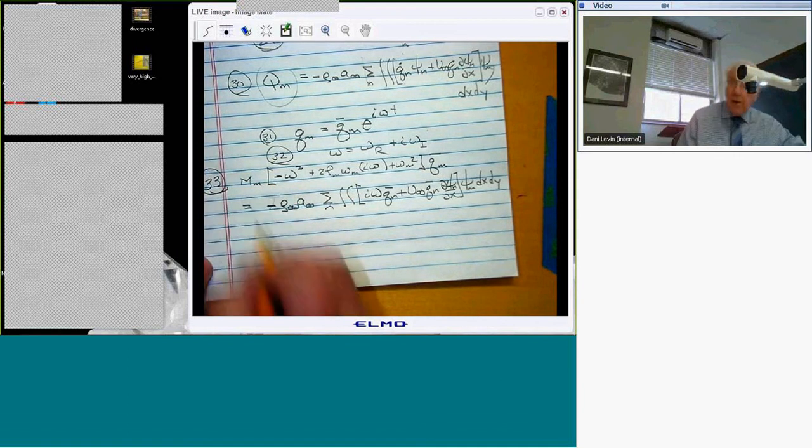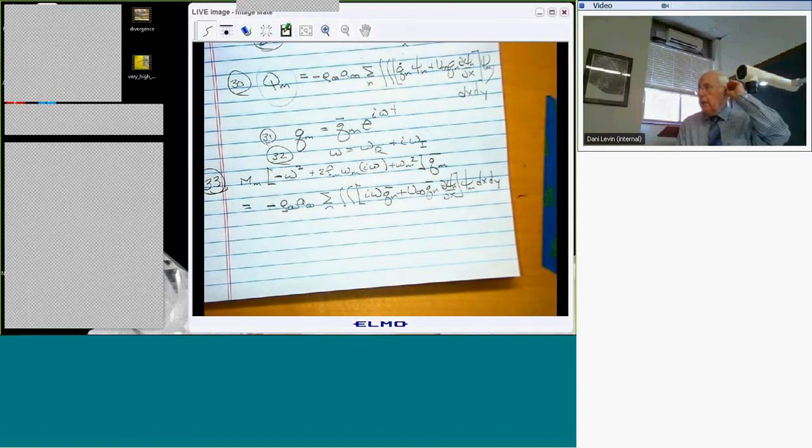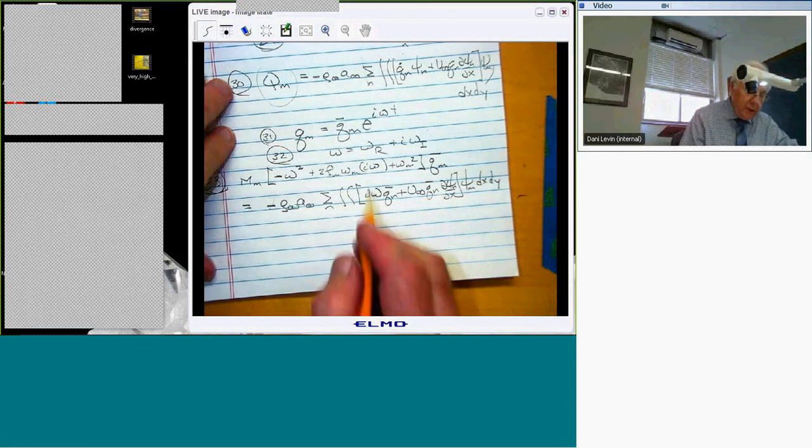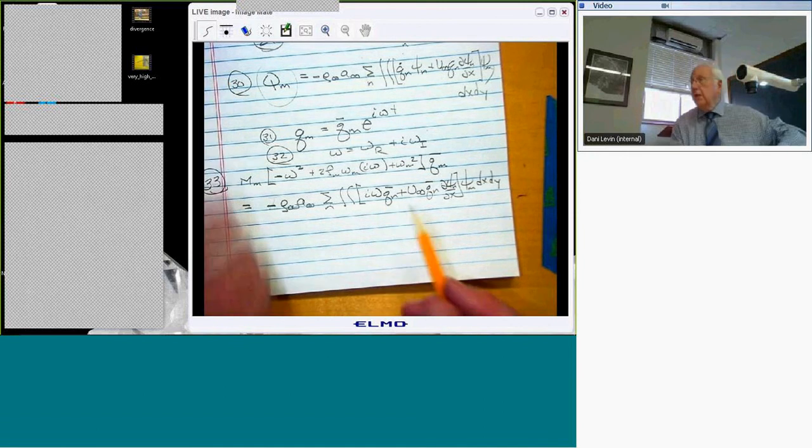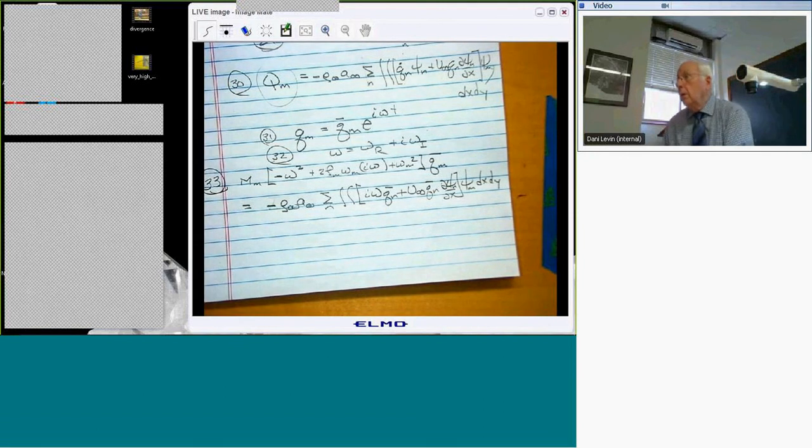We're going to write 33 in matrix form. We're going to put everything on the left-hand side because everything depends on q sub n bar, right? This is now a set of linear algebraic equations in q n bar. We're going to seek the non-trivial solutions. So we want to write this as some matrix multiplying the column vector of all the q sub n's, and we want to set the determinant of the matrix equal to 0, because that will give non-trivial solutions.